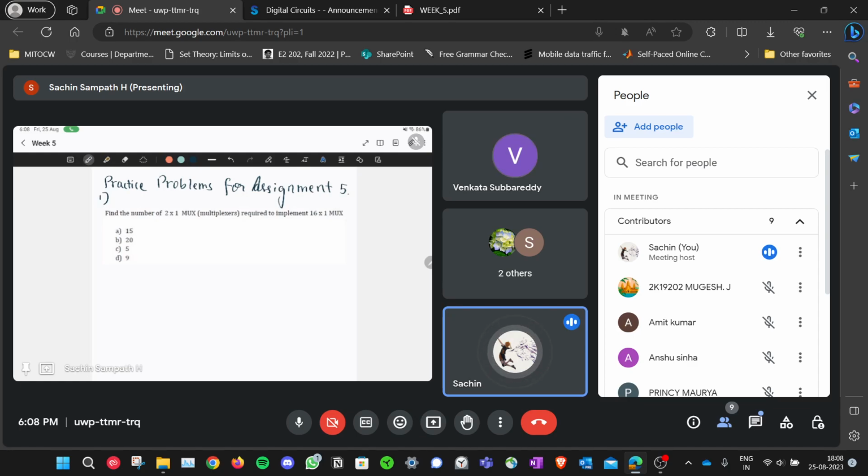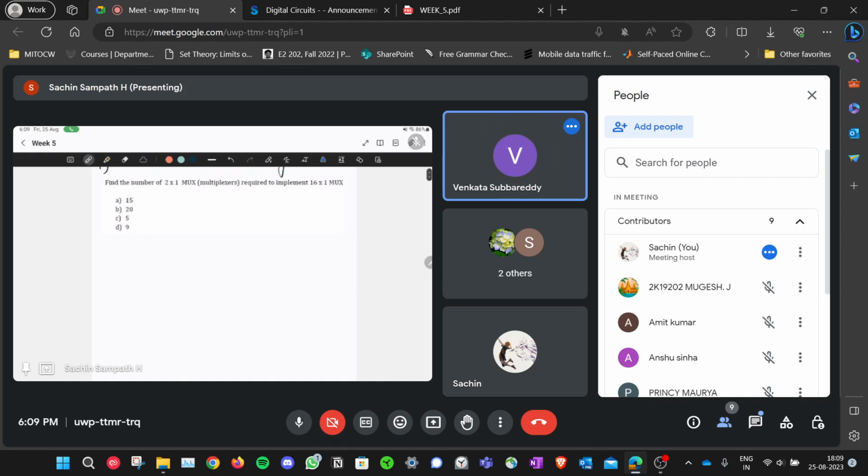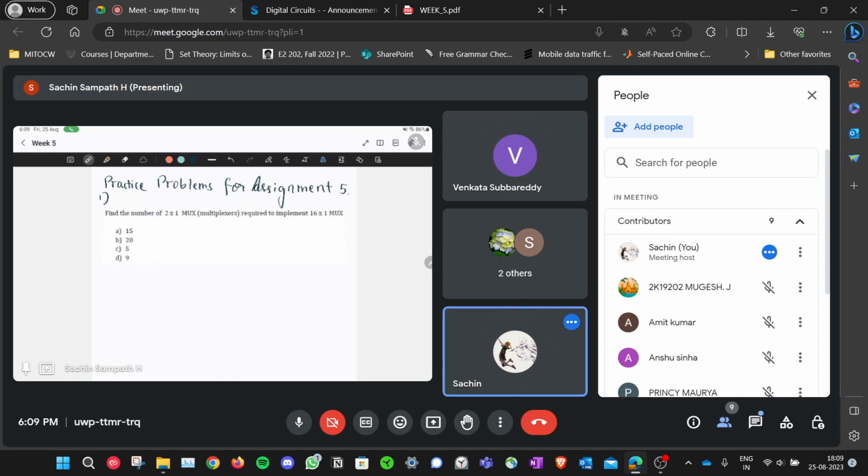The circuit for two numbers is shown in the lecture, right? And then you'll have to use two of those. You'll have to use three of those, I guess. No, you'll add A and B with one adder. You'll add C and D with one adder, and the results of both of them you'll add with another adder. You will need three adders.